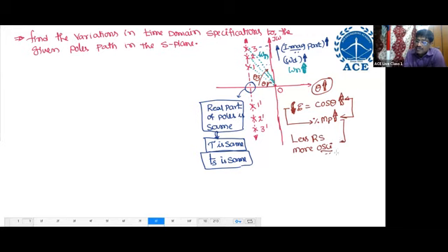Whenever the peak coefficient is very, very large, blindly we can say that the system is less relatively stable and more oscillatory. Finally, what I can conclude about the vertical movement of the poles is this: as the vertical movement of the poles increases, zeta decreases, and the system becomes less relatively stable.